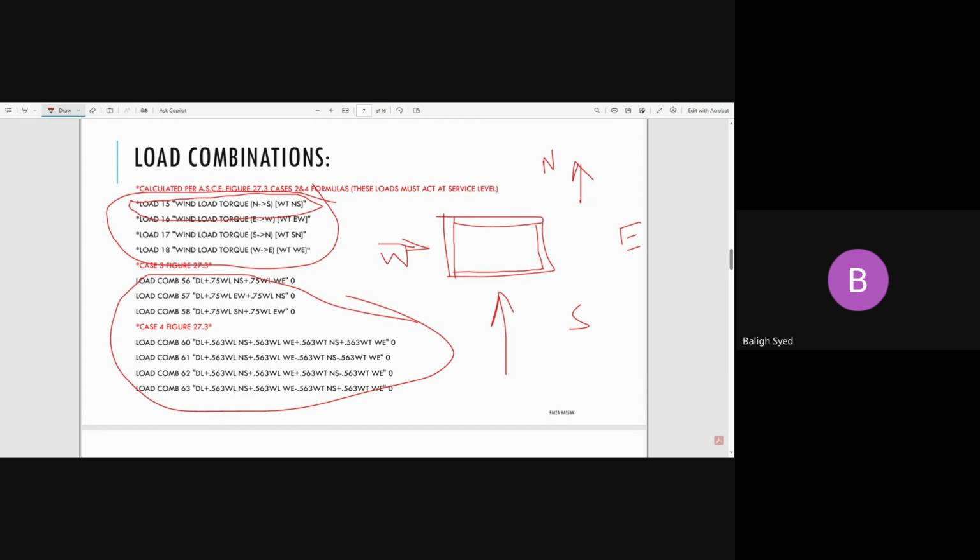And all of them, still today in 2025, I'm talking to you, we use ASD, the allowable stress design method. Only conventional concrete is designed with LRFD, not PT. Remember my words. Only conventional concrete, and not unconventional concrete. I'll explain what I mean.